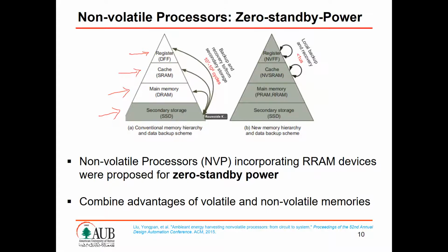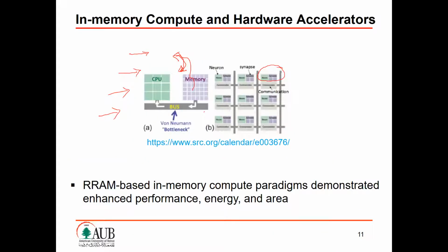And when we are doing a program, we really move or carry the data from one place to another, and most of the computations happen directly between the SRAM and the cache. So non-volatile memory we can integrate with the SRAM, the memristors, so that we can back up the data into the memristors, or we can perform directly in-memory compute using the novel memristor-based associative processors or vector-like processor. But this basically helps us in standby.